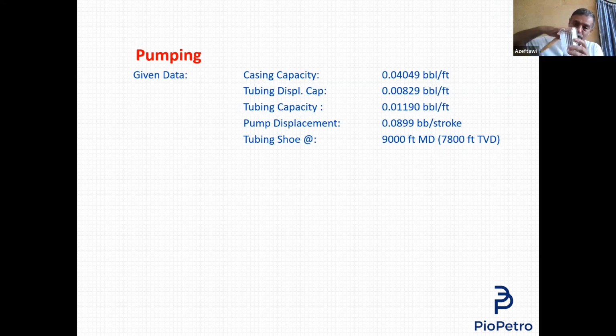This well is full of water. So the moment this production tubing enters, water comes out. This is the water displaced, by the metal thickness of this production tubing. So by the time I finish running the production tubing, 50 barrels is out. What is this 50 barrels? This 50 barrels is the tubing displacement volume. This is the volume displaced by the metal thickness of the production tubing I'm running.